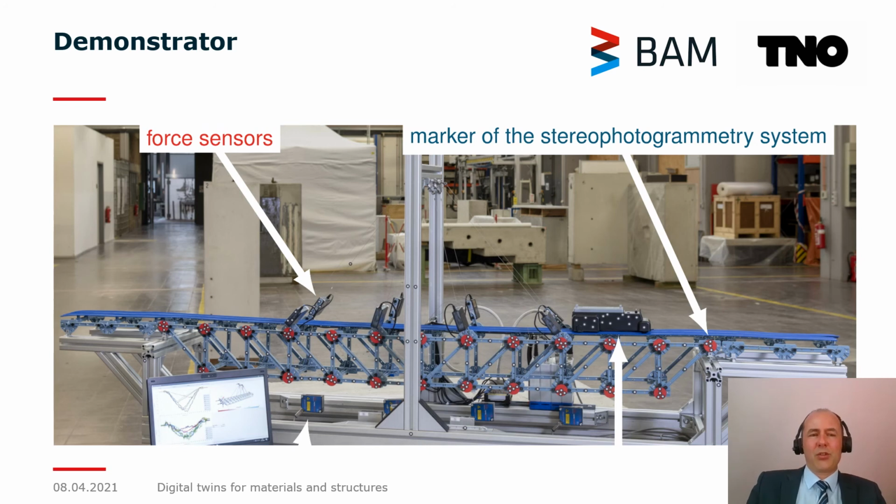All right, now I would like to show you an example that we set up in order to show you a little bit what a potential digital twin might look like. So we've set up here an example bridge in the lab. And you see here, there is a car that's passing over the bridge. This is this one here. We have a couple of sensors. So below here, you see laser sensors. They're at the bottom and measuring the vertical displacements at 6 positions. In addition, we have in the cables, I don't know if you see that, so those are cables here, we have force sensors that allow us to measure the forces within those cables.